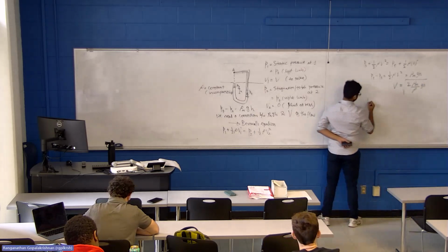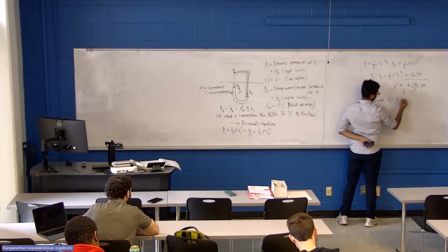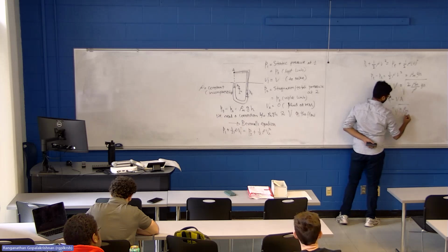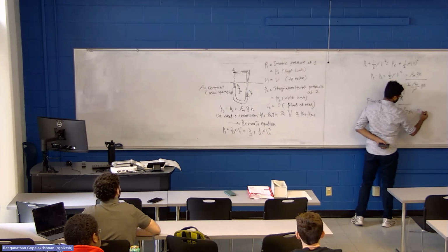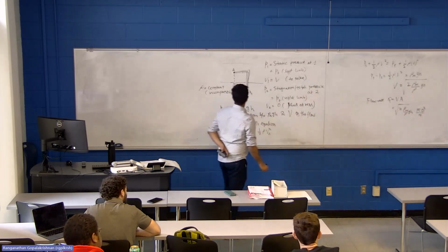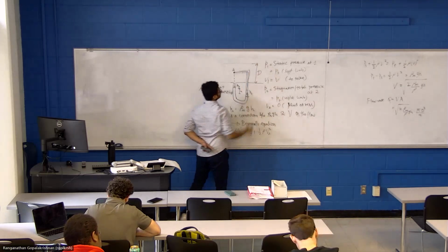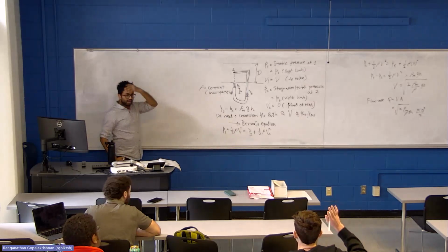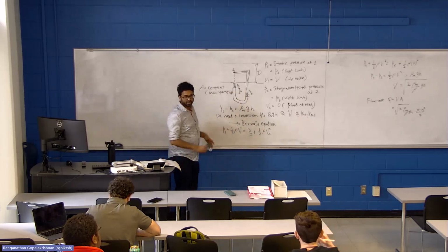And if you want flow rate, Q equal to V A, which is square root of 2 times rho m over rho g h multiplied by area of cross section pi d squared over 4, where d is the diameter of the pipe. Here rho m is the density of the manometer fluid, correct.